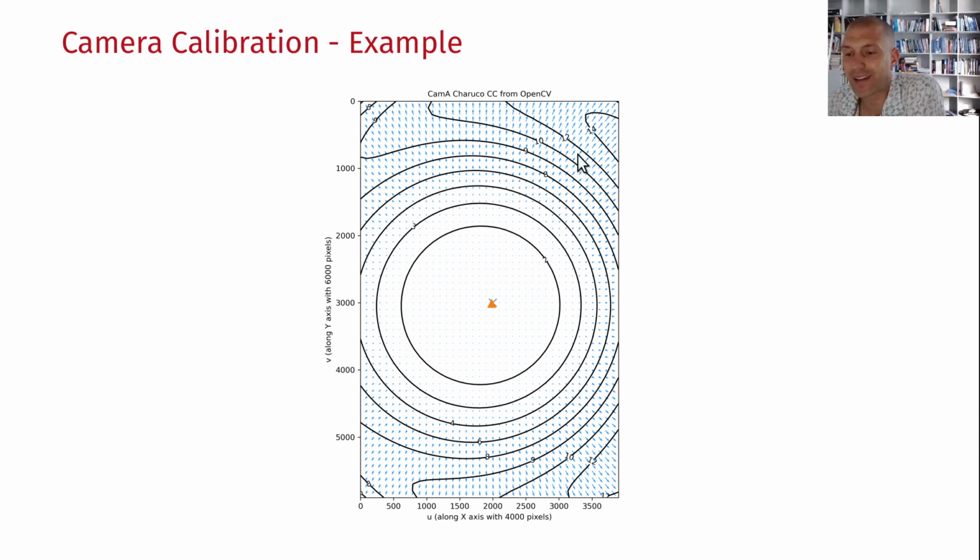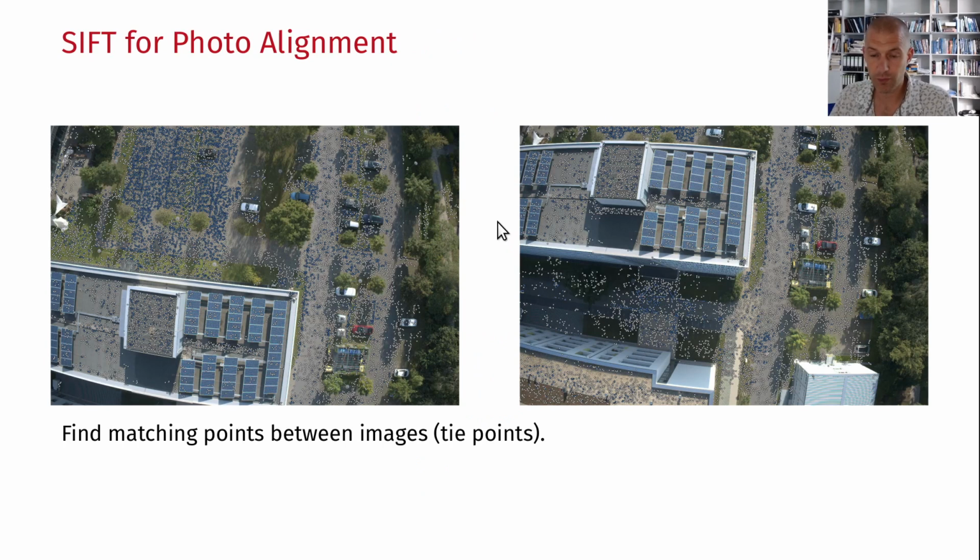And usually it gets more distorted towards the corners just because of the aberration of the optics that you end up having. So the point that I want to make here is that you can have 10, 12, or sometimes even 30, 40 pixels of distortion in the corners, and you need to be able to correct for them. Because if you have a 40 pixel offset in this corner and you're linking that SIFT point with a point that is somewhere in the center, that point would be 40 pixels away. So your camera location would be different. I just want to make this point really clear.